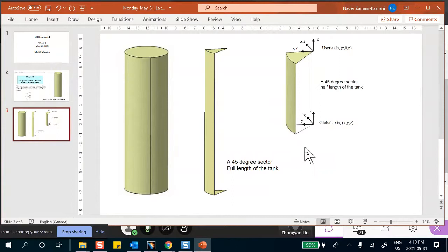Now, when we did the rotating disk problem a couple of weeks ago, we didn't have that issue, because there, in the book, I told you I throw a curveball at you, but I said don't worry about it, use surface slider. Surface slider doesn't care what the orientation is. There's a surface there, but you cannot use surface slider in shells, because these symmetries are edges.